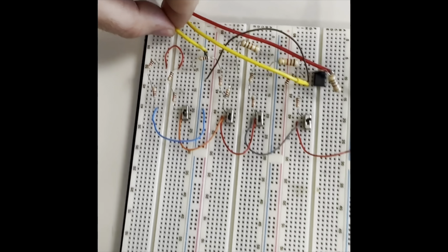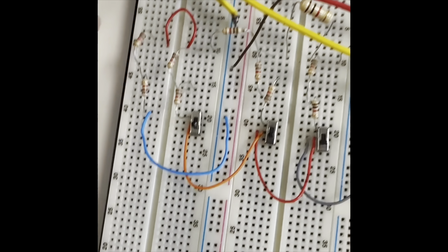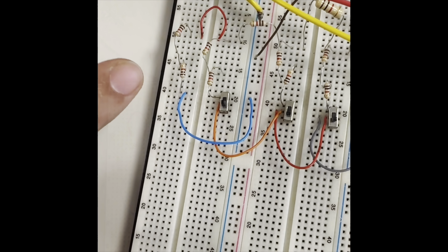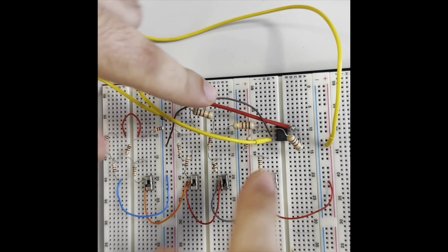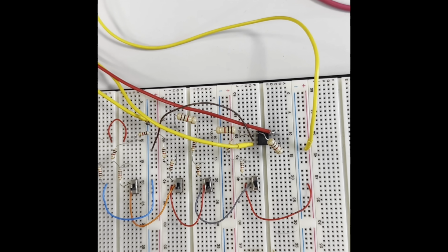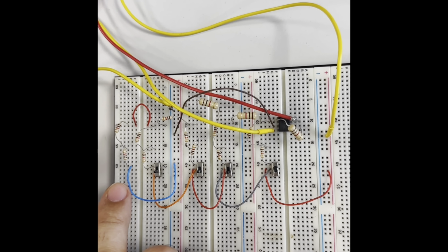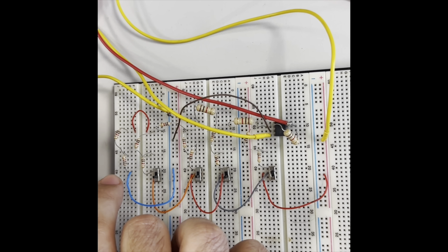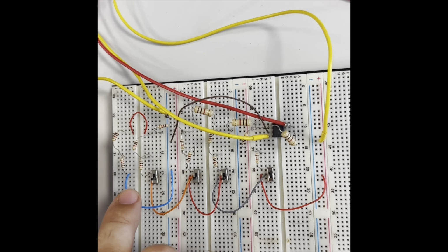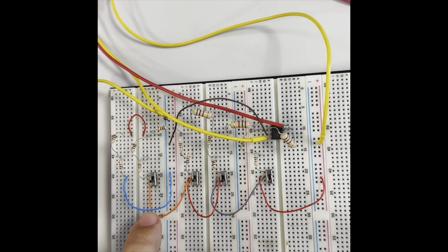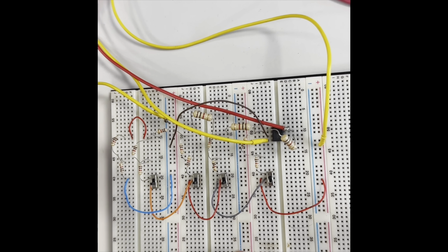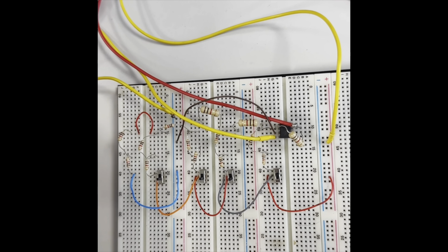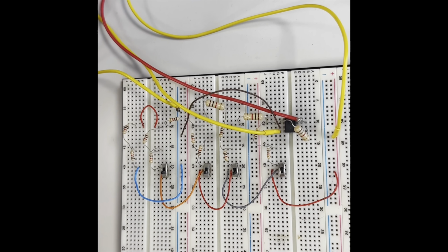So our ground cable is grounding our first 2K resistor, which we obtained by connecting two 1K ohm resistors. Also, this ground cable connection grounds our op-amp's non-inverting leg, as you can see. We used 5 2K resistors by connecting two 1K ohm resistors in series, and four of them, this one, this one, this one, and this one, are connected to four different switches, which we are going to use for giving different binary numbers and obtaining analog signals.